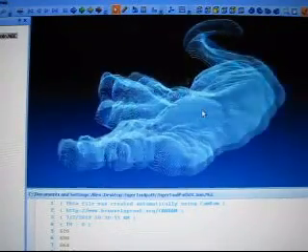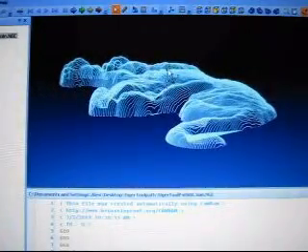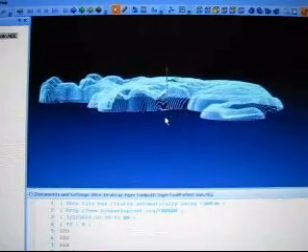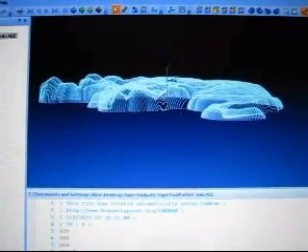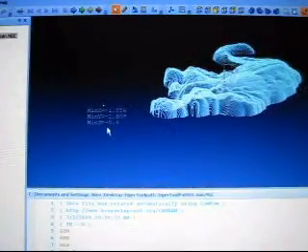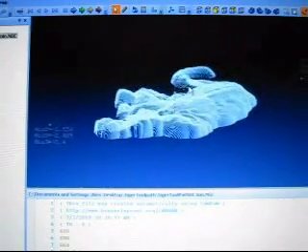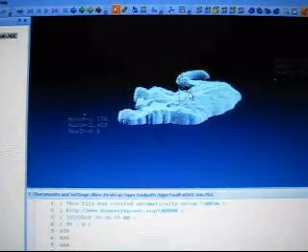Alright, now you'll notice right off the bat that the tool is going to drop a rapid motion right on the floor of that part. Okay, let me show the bound box for it. Our Z is -4, but the top of the Z is 0. We don't have that extra clearance which I normally put in at 0.1 of an inch.